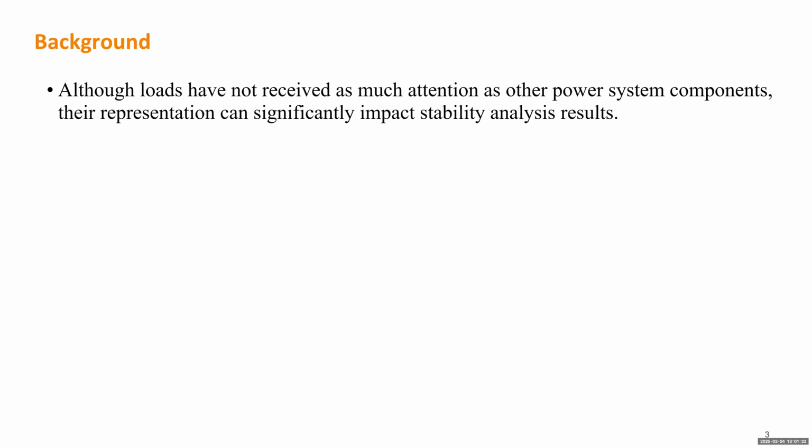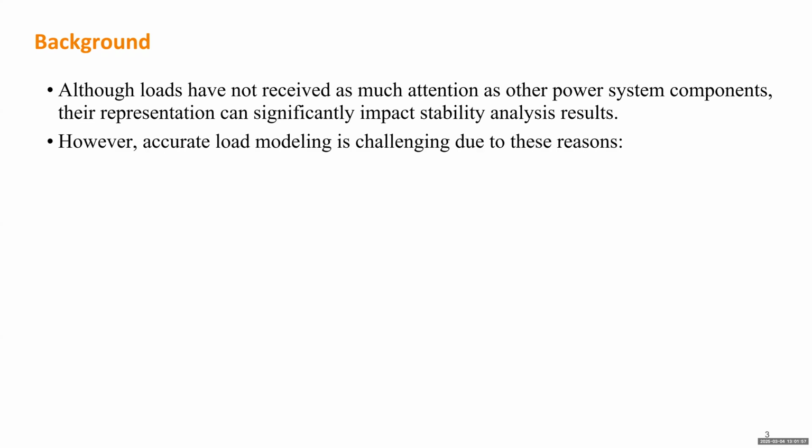Some background information about load modeling. Although loads have not received as much attention as other power system components, such as generators, even transformers, transmission lines, and some other controllers, if they're not accurately represented in the power system model, they will affect the accuracy of the stability analysis.